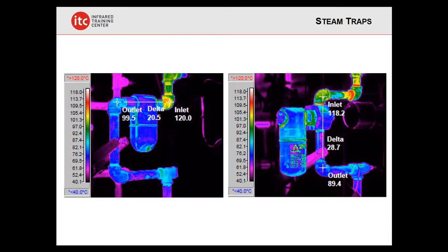That's right. Steam systems can be rather difficult to diagnose because the thermodynamics of steam in the entire system can play tricks on you. Actually, in these particular images, that clamp that you see on there is a clamp with an ultrasound detector on it, because ultrasound, in the end, does a better job of diagnosing these. But it generally requires touching, and so you can at least get a rough idea of the steam trap's condition with the infrared. But as I said, it can be a difficult thing to do because you could have condensate pressure backed up in the condensate line, or other traps blowing through, raising that pressure, therefore raising the temperature there too. So a small temperature difference versus a large temperature difference doesn't always really pan out.